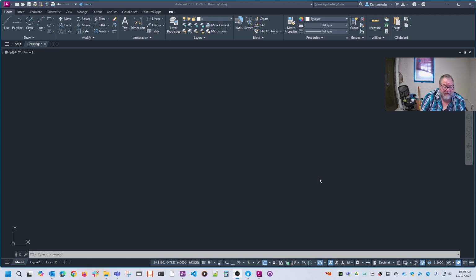And then whenever we export this to a GIS, all that data would go right into the GIS. What we found was that was kind of cumbersome, and the maps never really got updated properly. So we've kind of cut back and just do the unique identifier or the manhole number. That way they can maintain all the rest of that information in the GIS package instead of doing it in CAD. But we used to do it all in CAD as well.